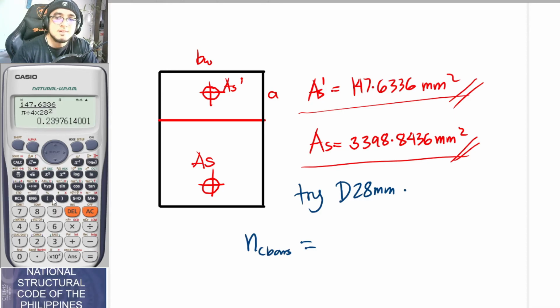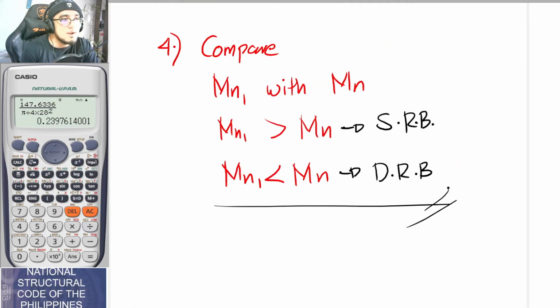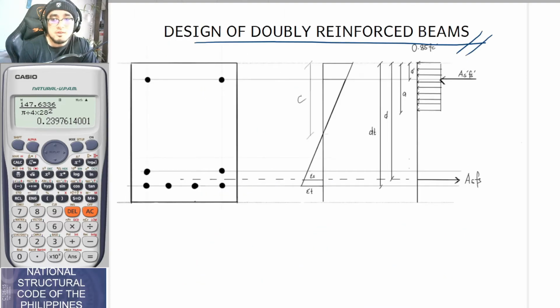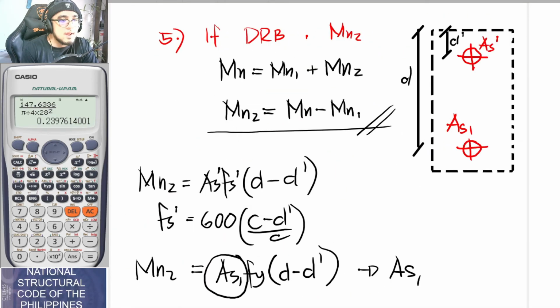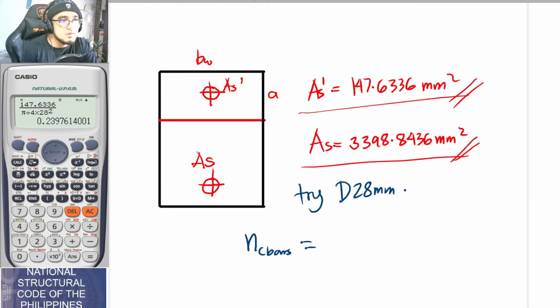So basically, you only need a fraction of one rebar as per As required. However, the minimum number of pieces that we can put is 2. Because if it is 0.28 and you won't round it up, it is not allowed in a special moment resisting frame. So for 2 pieces and below, you must provide 2 pieces. So with that, I will be providing 2 rebars.